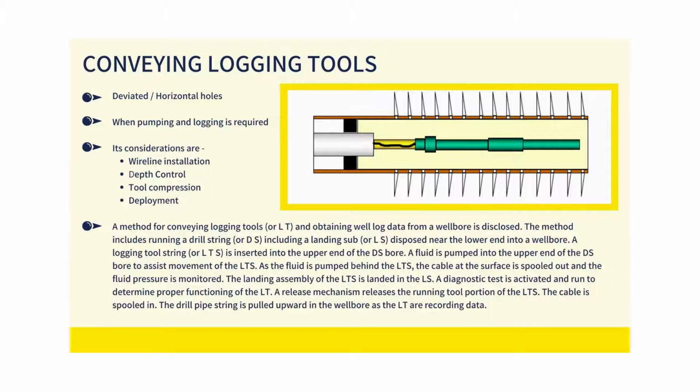A method for conveying logging tools, or LT, and obtaining well log data from a wellbore is disclosed. The method includes running a drill string, or DS, including a landing sub, or LS, disposed near the lower end into a wellbore. A logging tool string, or LTS, is inserted into the upper end of the DS bore. A fluid is pumped into the upper end of the DS bore to assist movement of the LTS. As the fluid is pumped behind the LTS, the cable at the surface is spooled out and the fluid pressure is monitored.